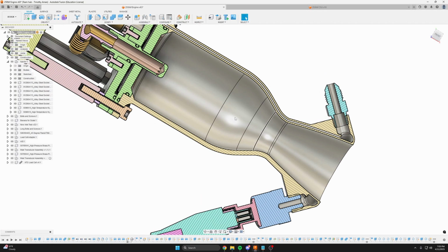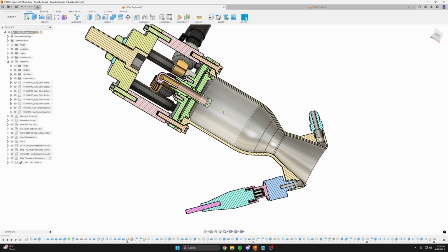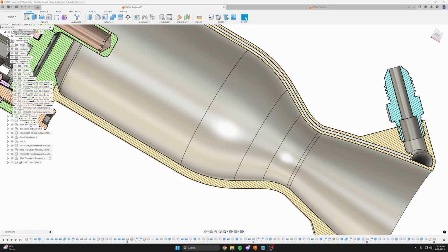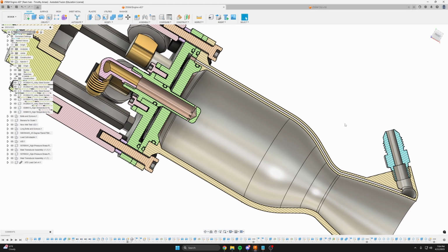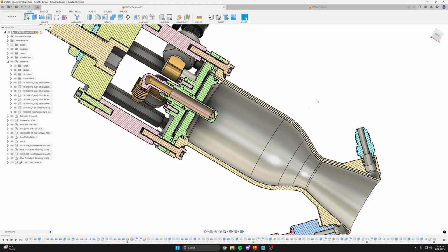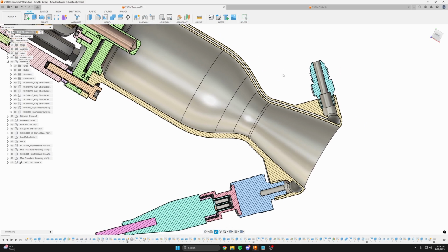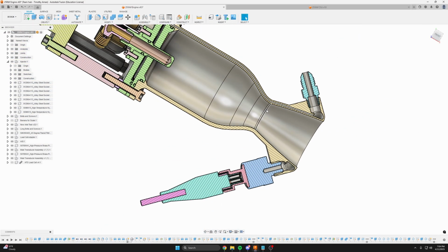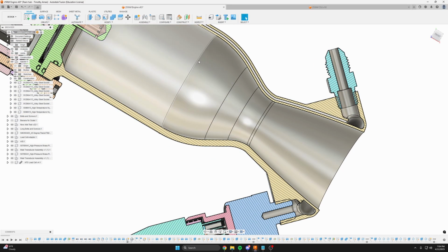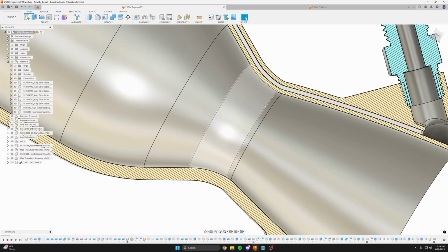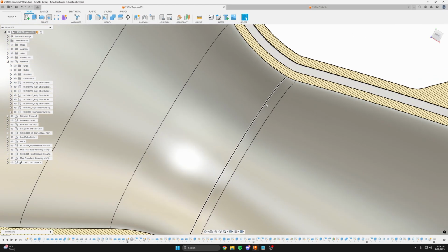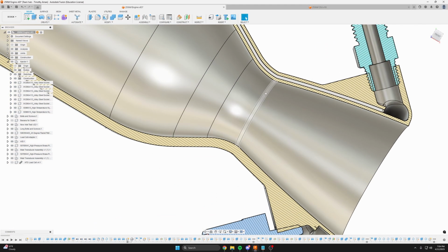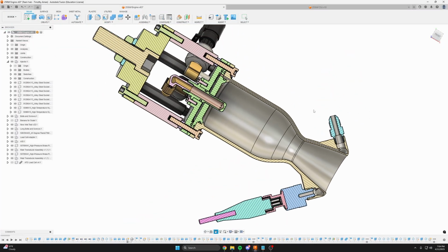Your worst case is either going to be the main combustion chamber, where the pressure and temperature are the highest, but the heat flux isn't as bad because you have more surface area. And then the throat is where the heat flux is the worst. Even though the temperature and pressure have dropped a little bit, the heat flux is the worst. So I would look at the output of your RPA thermal sim,